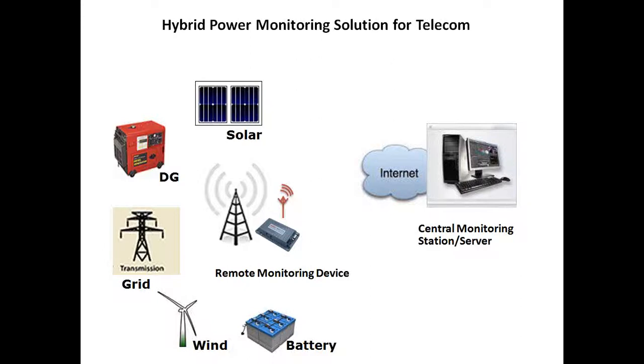If you pry open this setup, there is a remote monitoring device, just like you have a remote monitoring device in other applications. And this in turn is connected to many instruments in the telecom shelter. And these telecom shelters may have AC energy meters, DC energy meters, control relays, or other power monitoring units. It could be anything, and potentially it could be connected through wires, or it could be connected through wireless, such as Zigbee technologies. And all the data is continuously monitored 24/7, and it could be monitored every 10 minutes, or on interrupt, any relay changes, immediately that information could be monitored.